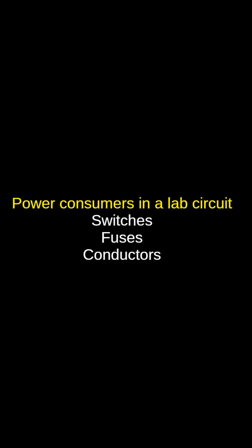There are several methods for determining total power rated in watts consumed by a series circuit. In the first method, we multiply the source voltage times the current value of the circuit, E total times I total, or voltage total times current total. Another easy method is to multiply the current squared by the total circuit resistance, or I total squared times R total.